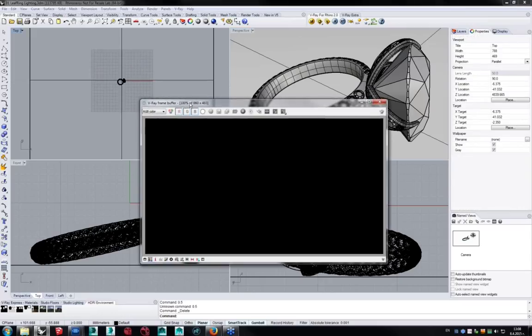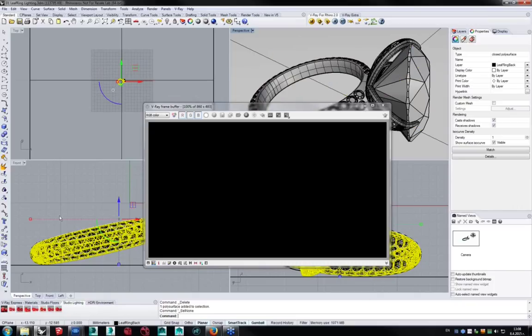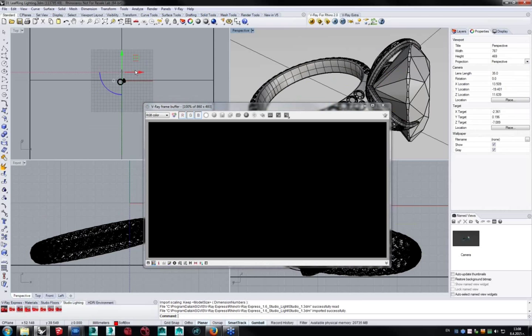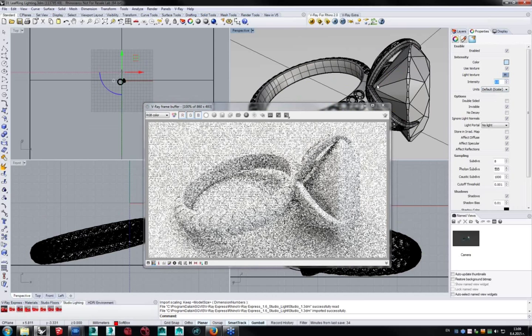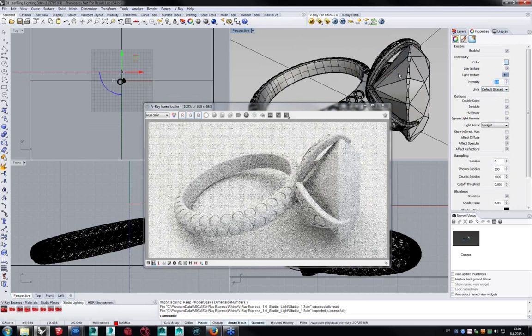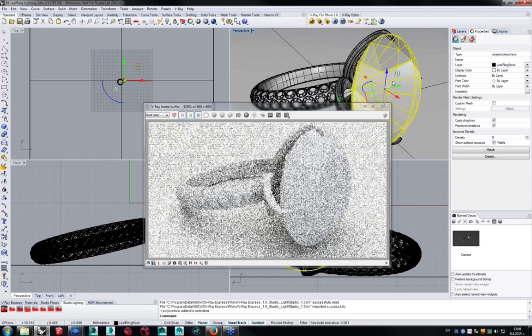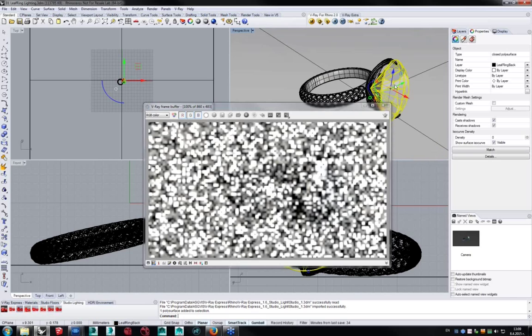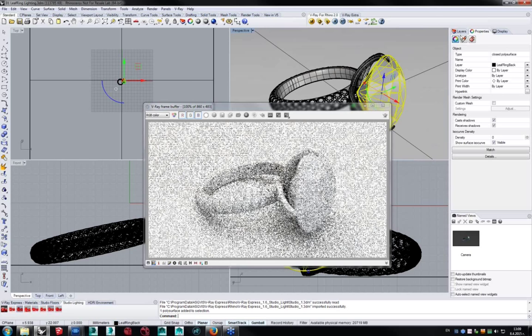Okay, so another way of lighting the scene would be to use the studio setup. So let's create a studio setup. Now these are just predefined lights, again like the dome light, that you can use to do that. So I just lower that intensity, and there we go. Now once you're happy, well, let's say the gem is big enough or small enough, or all the bezels are in place like you want them to be, you can start shading, but I will come back to that in a few moments.